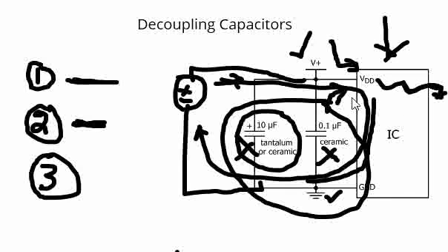Now let us assume a scenario where you have the capacitors very close. The actual loop between the ground and supply will be through this small area near the IC because of the decoupling cap that is placed there. This is another reason why we need to keep the cap as near as possible, so that you reduce the loop area of the current.